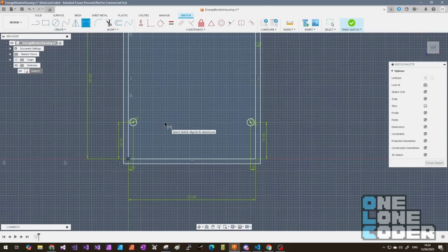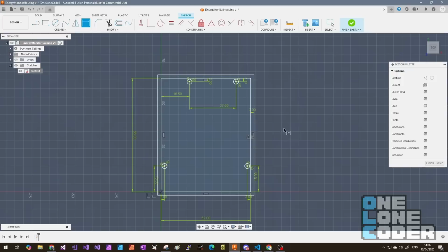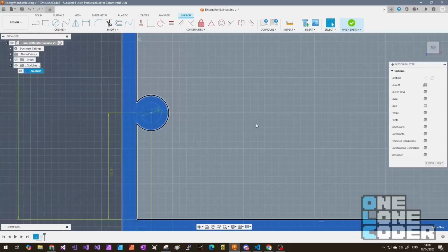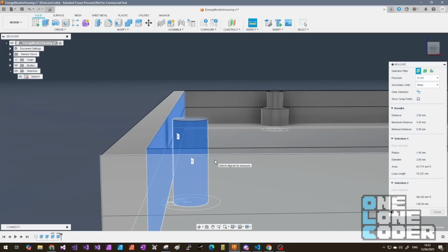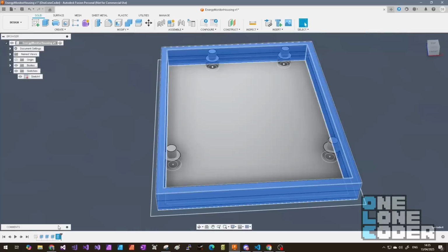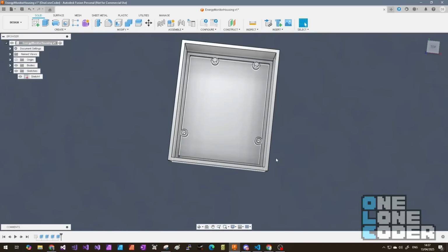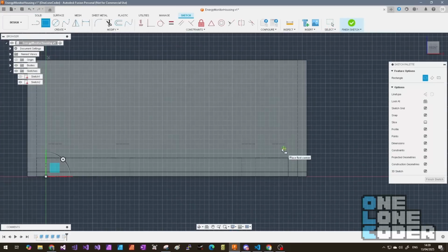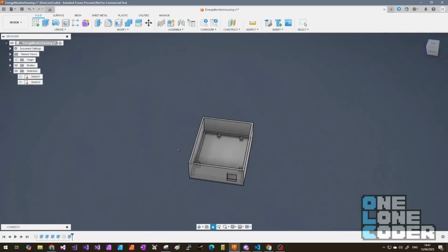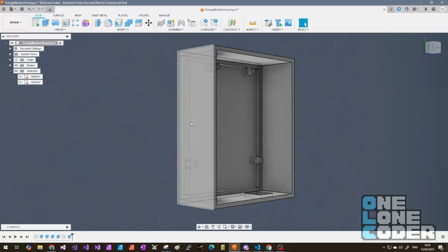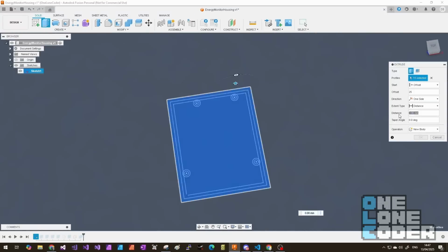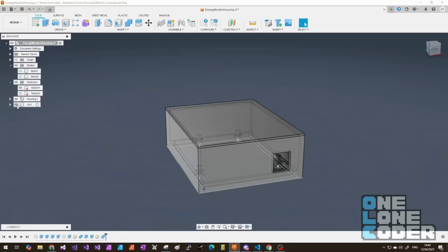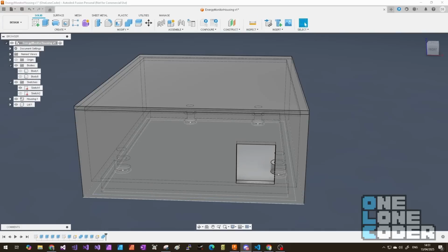To design the housing, I used Autodesk's Fusion 360. I'm familiar with the Inventor environment, and Fusion 360 is reasonably well priced for my needs. I started by designing the main chamber to house the ESP32 module and its expansion board, and you can see it's got these sort of 4 lugs that can sit the board properly. I then cut a small hole in it for the DC jack input. I made a lid which would work just by compression. There we go. Nice, that's the first part done.